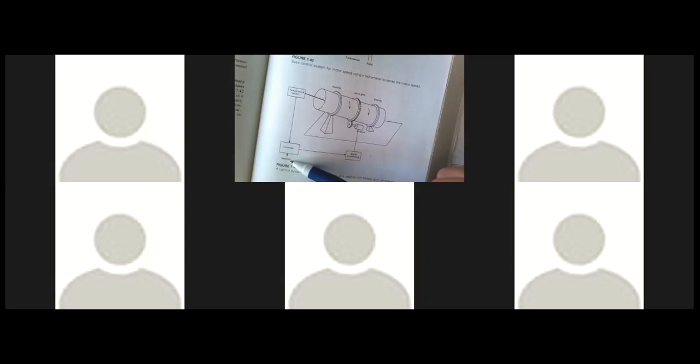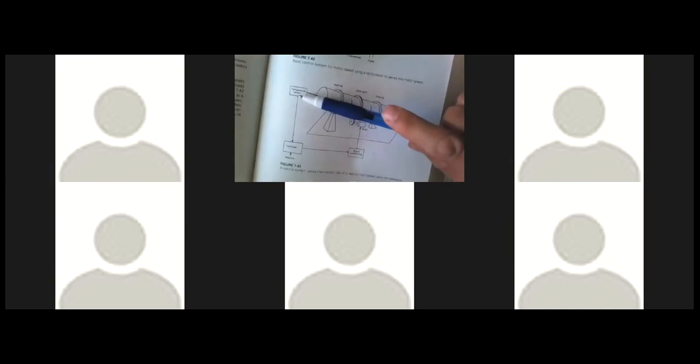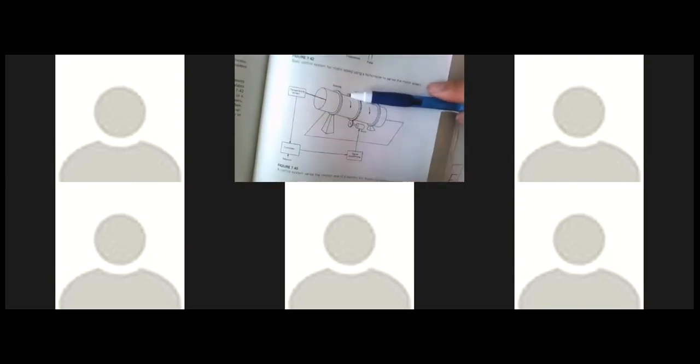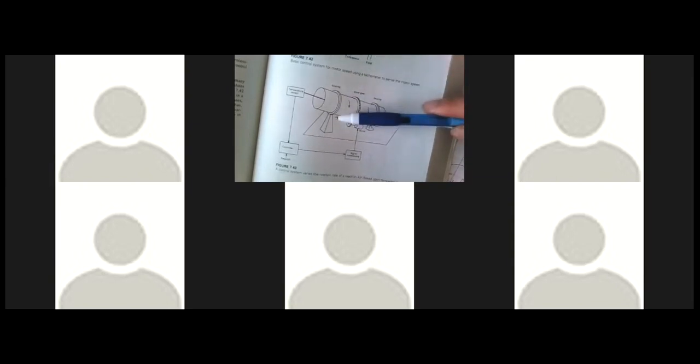So the operator will set, for example, 10 RPM. Why 10 RPM? Why not 1,000 RPM? You cannot do 1,000 RPM. This is a big house. 10 RPM or 5 RPM, whatever RPM you want to do. The RPM is decided by the temperature sensor. If it's too hot, you overcook your material, right? You do not want your material to be overcooked. How to prevent overcooking? You roll it a little bit faster. So you get your material away from the fire a little bit.